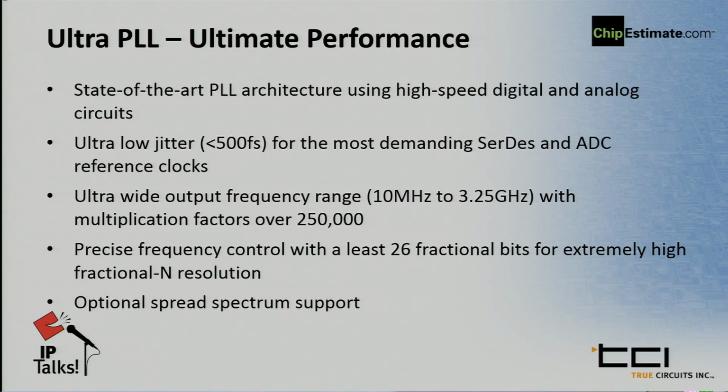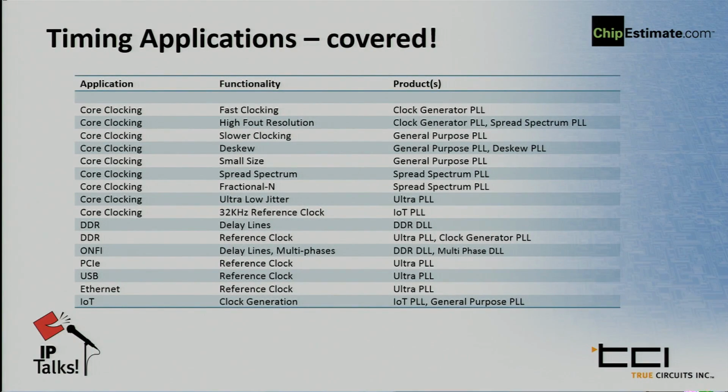Also has fractional bits, up to 26 fractional bits, so you can build a very precise frequency from any reference clock that you have. And that also allows spread spectrum support, where you're varying the frequency to spread the electromagnetic energy over a wider bandwidth.